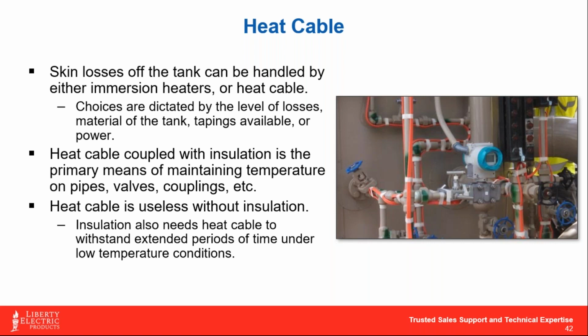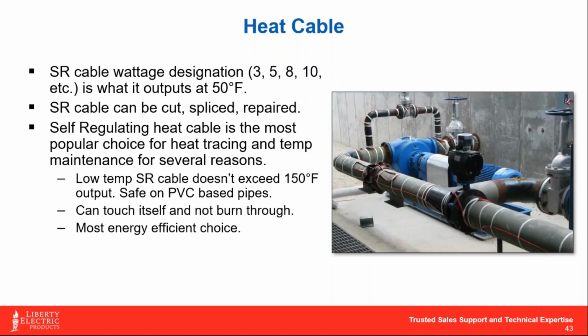Okay, so it's oftentimes a misconception that we're adding heat or can add heat to the process with a heat cable. When you're talking about Schedule 40 or Schedule 80 pipe, it's not going to happen. Especially once you put a flow rate behind it, you just don't have enough latency time for the fluid sitting in the pipe generally to affect its temperature change. So again, it's really just a means to offset losses off the system.